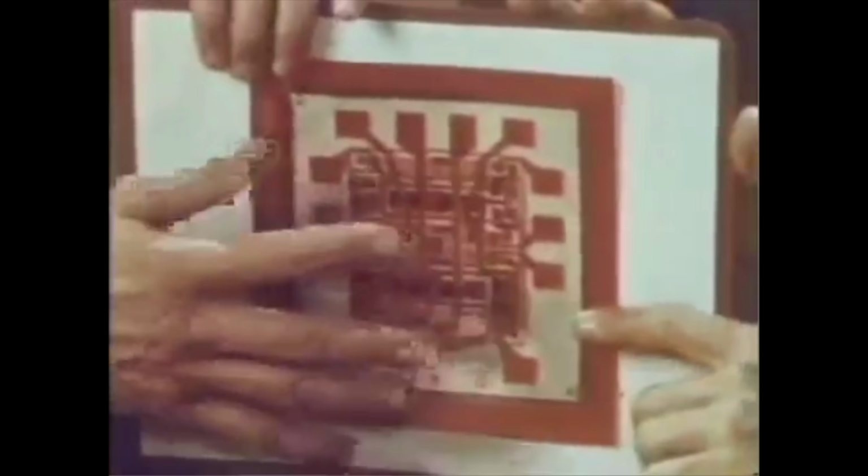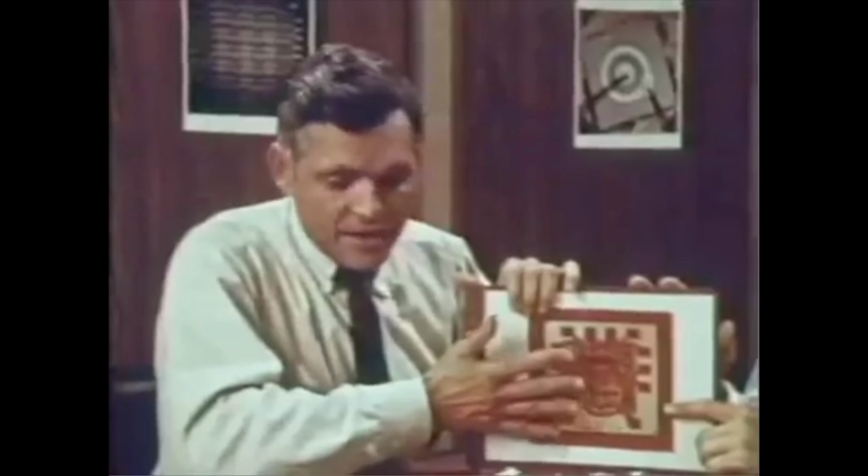Now, the artwork which I showed was only one mask, potentially. Here is the artwork in reduced plastic overlay version, which goes with a complete set to make an integrated circuit. There are 5 to 7 or even more of these potential masks. All of these must align carefully and precisely. These then will be translated into another set of glass masks, which will then be used for contact printing directly onto silicon wafers. In working with silicon, this is what you begin with: a silicon ingot.